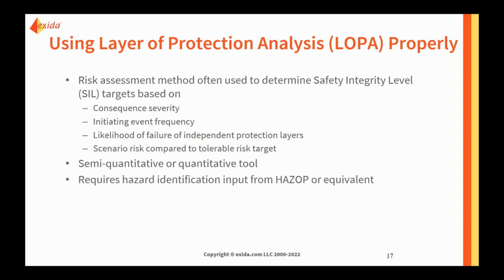tool in understanding whether or not we need an additional layer of protection of a SIL-rated safety function, or if we need a high demand or continuous mode safety function to sit right on top of the hazard and fail at an extremely low frequency, so that then that low failure frequency of our safety function translates into a suitably low accident rate that we observe on the back end in all of this.